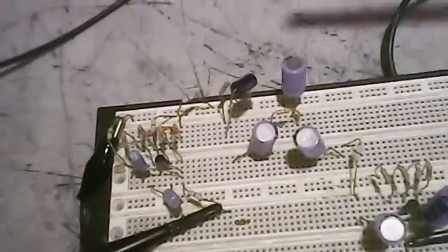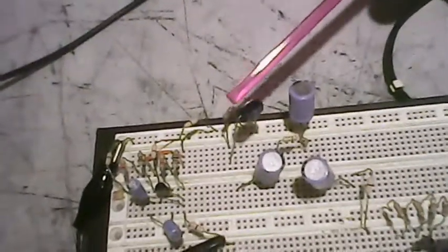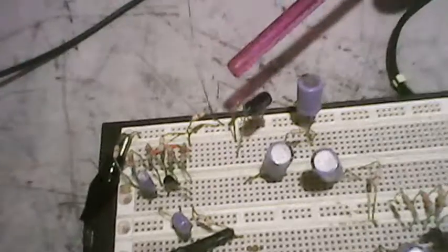So what that tells me is that this multivibrator circuit is putting signal on the power rail, and it's being picked up through the rest of the circuits, and it has to be decoupled from that. Okay, so for my decoupling network, I have a resistor and a capacitor to ground. I have the resistor going to the positive supply, and we'll look on the schematic and see what that looks like.